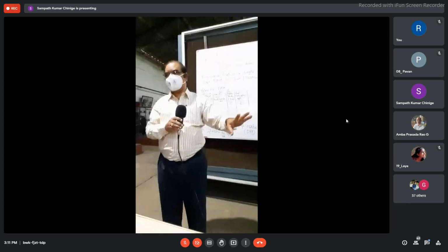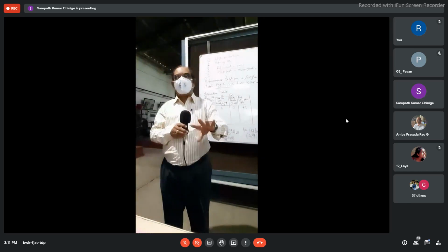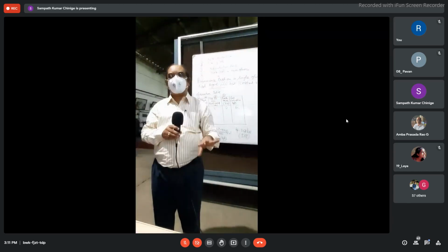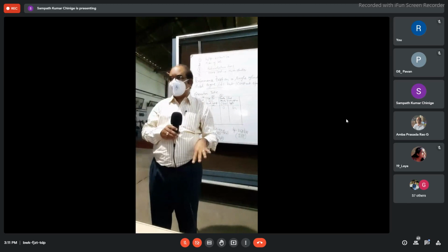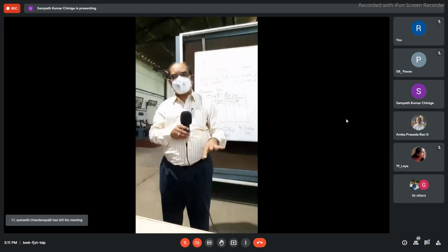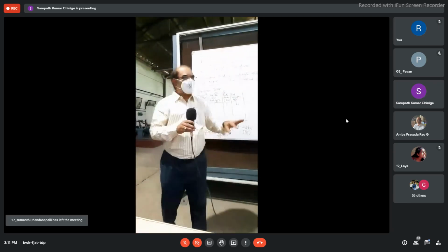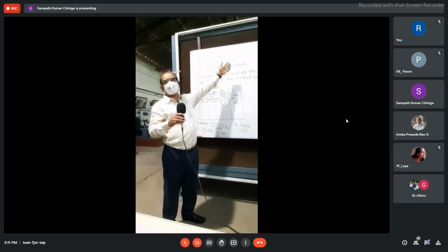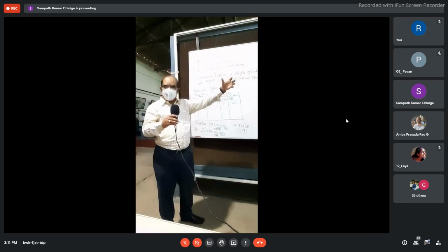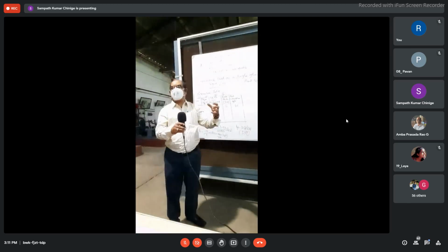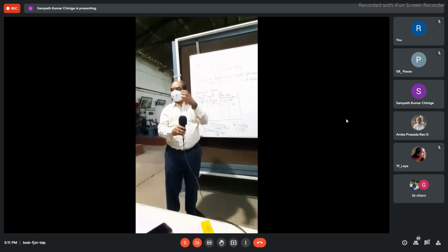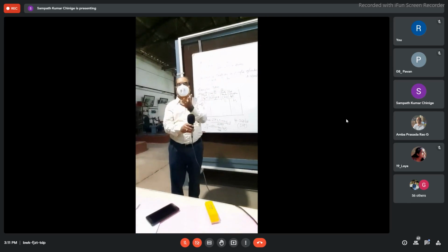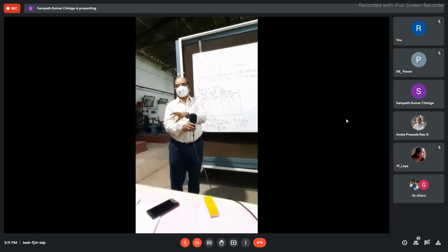The meaning is we don't supply the fuel, but we run the engine as it was running in the constant speed test. How much power it draws from the external source is an indication of the friction power developed by the engine when it was running with fuel consumption at the same speed.